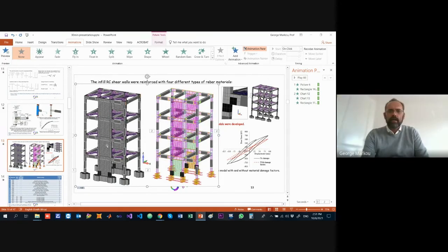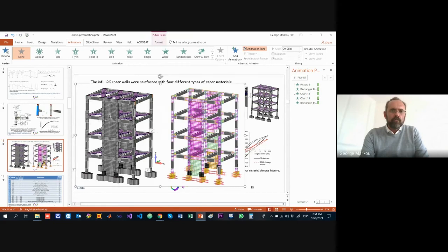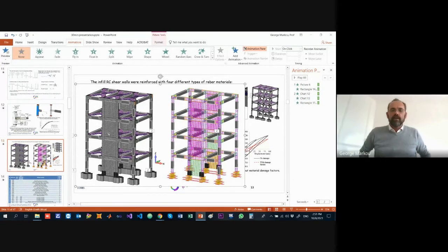And then connect them. This is what they did with the steel rebars, and they used epoxy materials, and then they used formwork and filled it with concrete. So they did connect them. They drilled and epoxied them into the other elements. This is what was done for the steel rebars in the testing project. And of course, what we did was to model that and capture the results and validate that we have the ability to capture it.